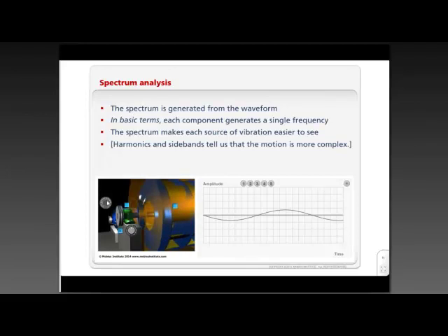So that's just that once per revolution vibration, which may come from the shaft due to unbalance, but maybe the shaft is bent, and there are other possibilities which would just give us this grey vibration from the grey shaft. And again, if there was more vibration, we see a change. And that's what condition monitoring is about, actually.